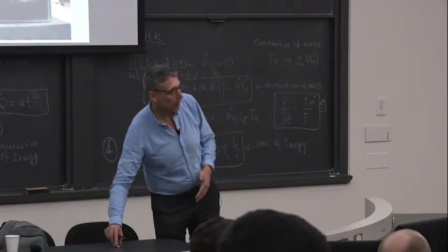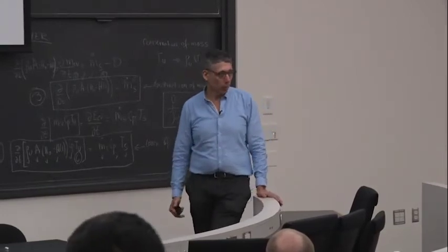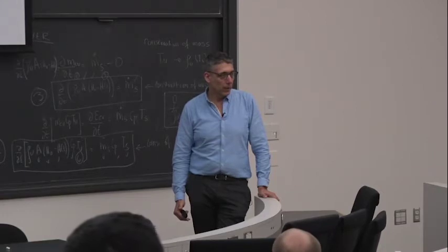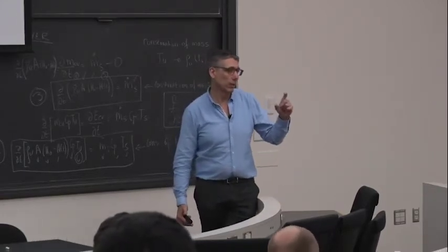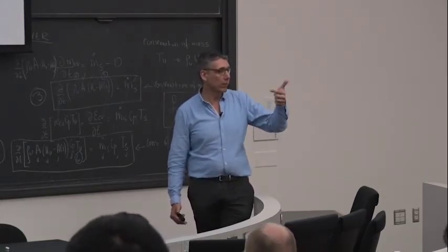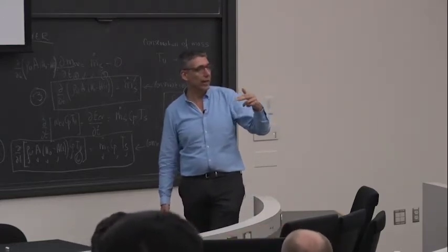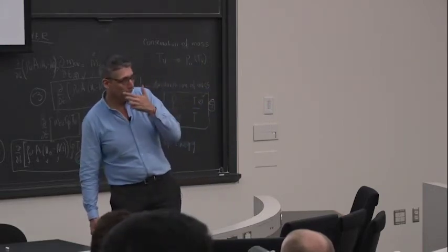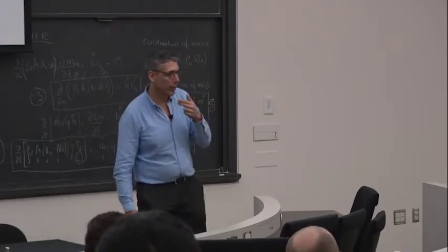Sorry, is it the density difference between your salt and the water, and that density difference is the same order of magnitude as the density difference of the smoke? No, it basically is the same Grashof number. So I do a scaling analysis, and it's a relationship of viscosity and buoyancy. So I change the density so that I maintain a certain set of non-dimensional parameters, which is fundamentally the Froude number, the Rayleigh number, and the Grashof number, mostly the Grashof number.